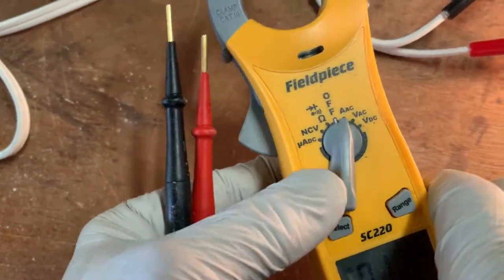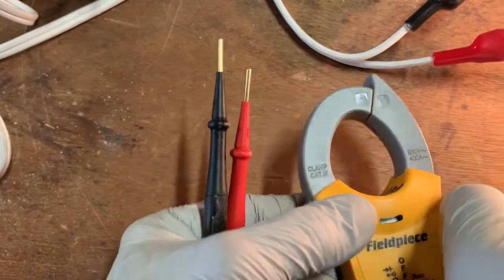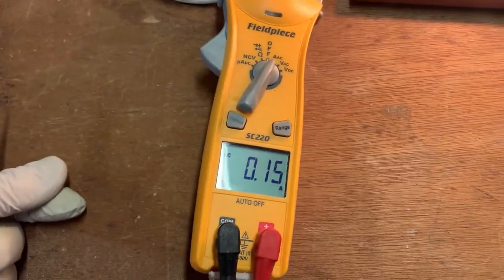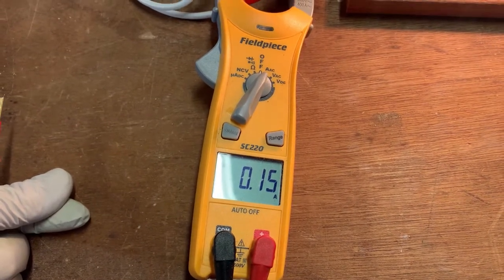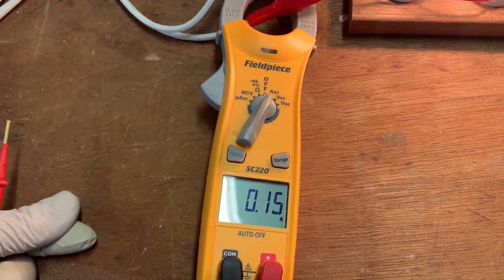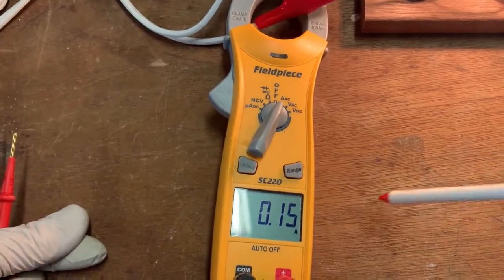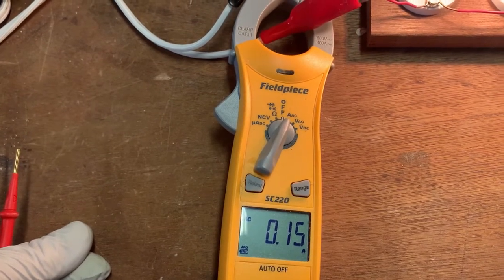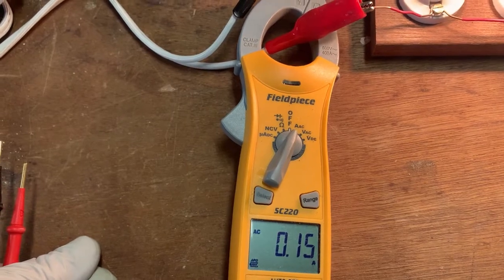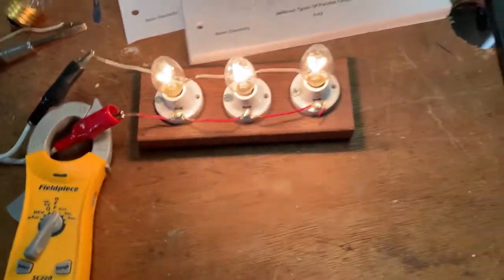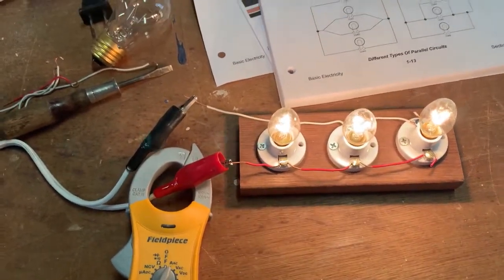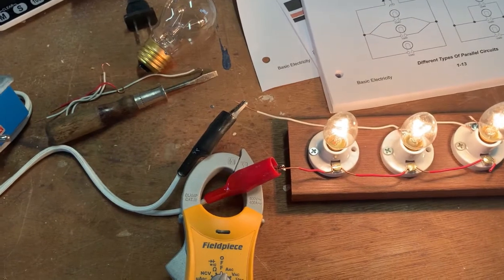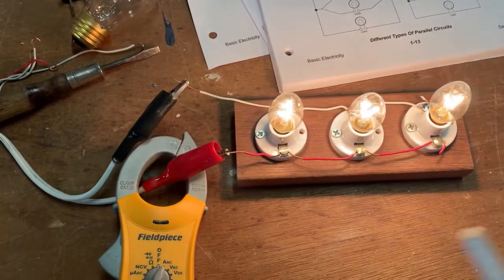And what about amperage? We turn it to amps AC, which is the clamp feature on the meter. We put it around one of the wires. And notice, remember the series lamps had almost no amperage. Very little power was being drawn, which correlates with them not being very bright. But in this case, we have a tenth of an amp, at least 10 times more power being drawn than when the lights were wired in series. So just from that, you might say that series is a way to save on electricity, to conserve electricity. I don't know in what way that's used, but that would certainly be something that could be designed into many things.